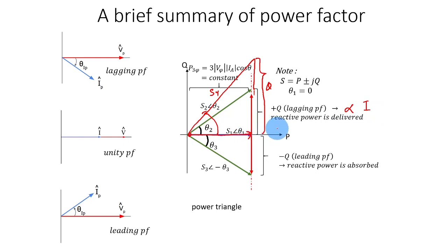that's why a more lagging power factor is not really that desirable. The most desirable is unity power factor, the best one, because you don't have to export any Q, and Q doesn't bring any profit. So it is better for the utility to have it as close as possible to unity. But sometimes, when it happens at let's say 0.6 or 0.7, the generator has to work harder to supply more current, but the utility is only getting profit for the same power.